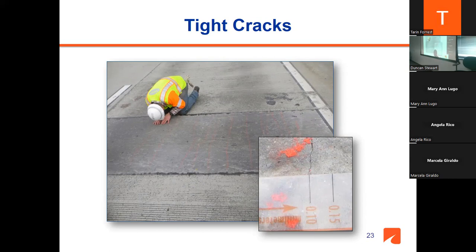And then you put a little bit of fiber reinforced concrete in it? No, actually, this concrete has the fibers in it. When we place it, it has the concrete and the fiber. But when the concrete cracks, the fibers start holding the system together because it is very strong.